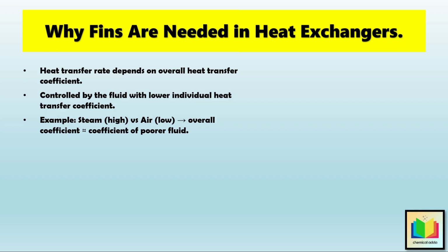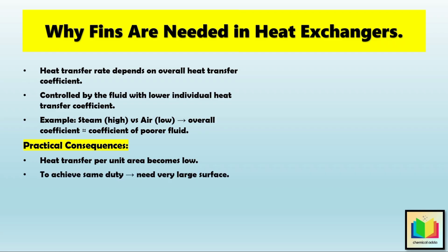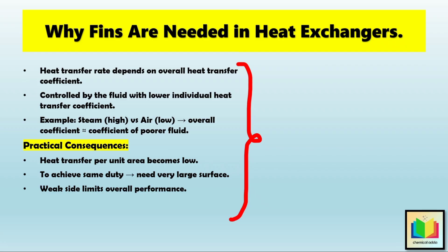But what will happen because of that? The first practical consequence is that the ability of the heat exchanger to transfer heat per unit area becomes much lower. Then, to achieve the same heat duty, the exchanger would require a very large heat transfer surface. In other words, no matter how good one fluid is at transferring heat, the weak side limits the performance of the entire system. And therefore, to prevent the design from becoming expensive, fins or other extended surfaces are used in heat exchangers.